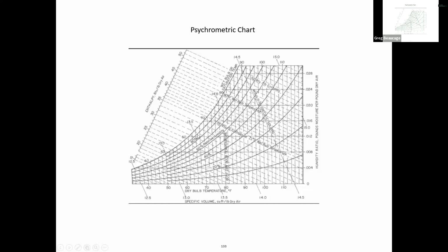Then the dew point is like if you go over here for some percent water in the thing. So you have the temperature, the wet bulb temperature, and the dew point. For the wet bulb temperature, you have a thermometer with a rag on it that's soaked in water. Sometimes you see a thermometer with a hoop at the top. I don't know if you've seen that. You put the hoop on a stick and you swing it around until it reaches a certain constant temperature. That's the wet bulb temperature.